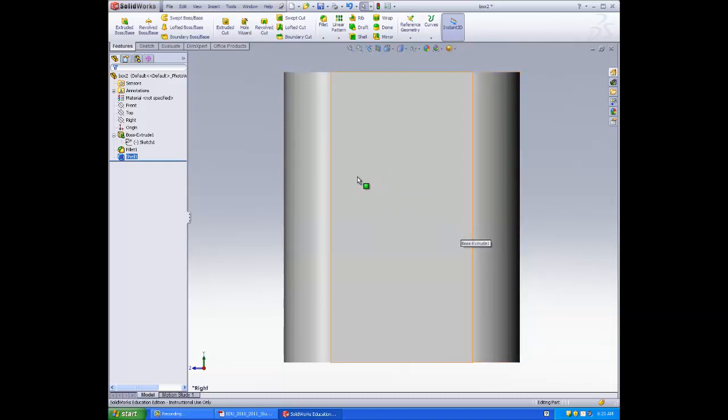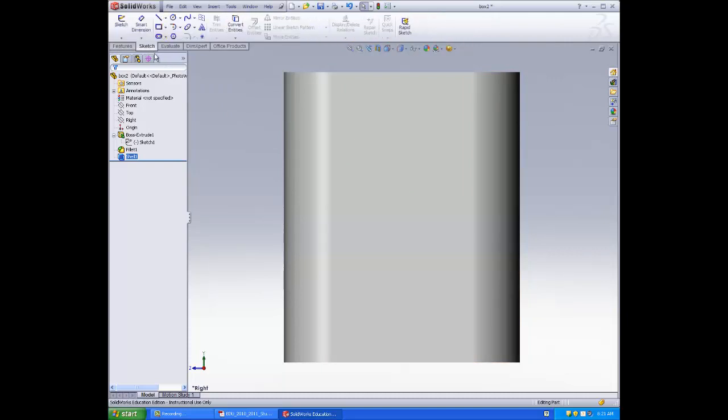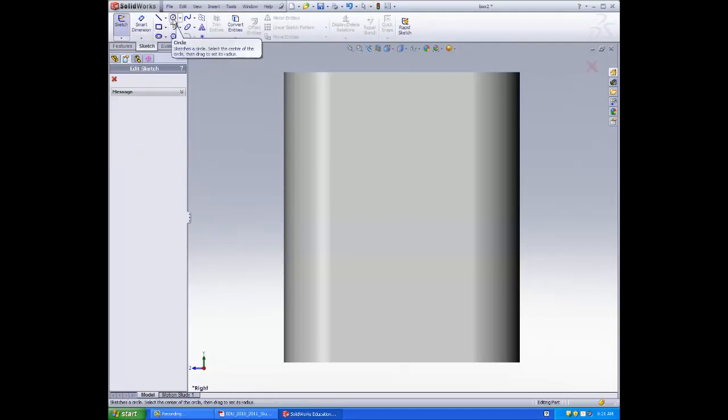Open the sketch. So we're going to go back up the sketch here. We're going to click the sketch on the sketch toolbar. And we're going to pick the circle. Position the pointer where you want the center of the circle, and then click the left mouse button.